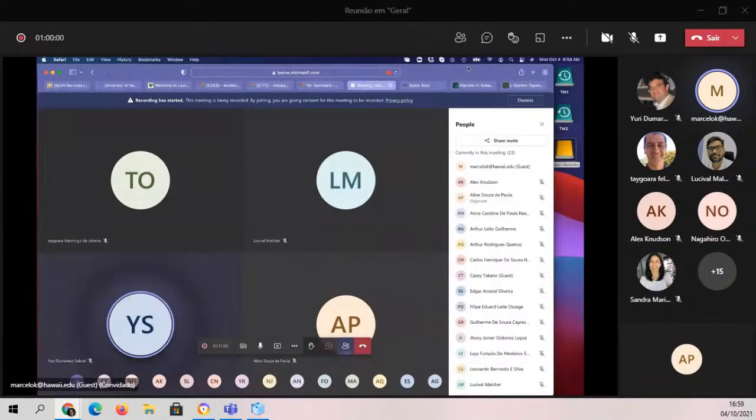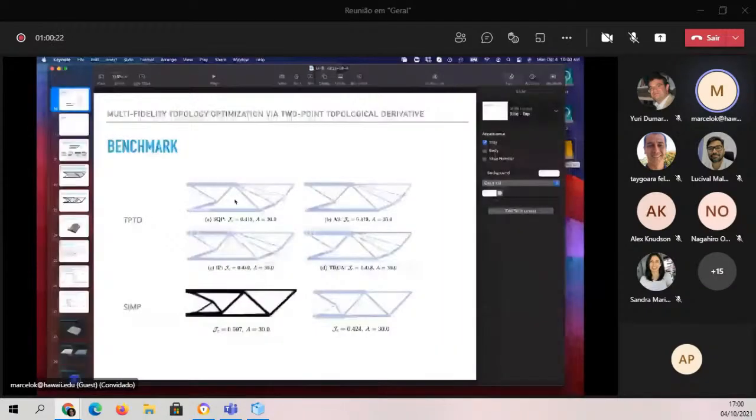Like, for example, if you want to minimize or maximize perimeter, right? Of course, if you don't put any constraints, there is no solution, right? That's right, yes. So if you put a constraint on the smoothness of the perimeter, then you get solutions. But no, I understand entirely your point. But of course, in a sense, that's the intent of SIMP. But even SIMP will have multiple solutions. So for example, SIMP here, if you don't filter, so SIMP uses a filter.